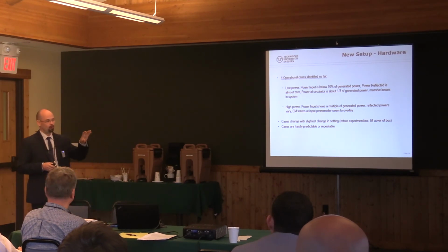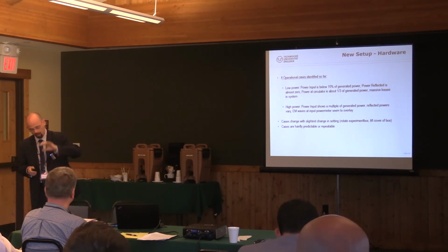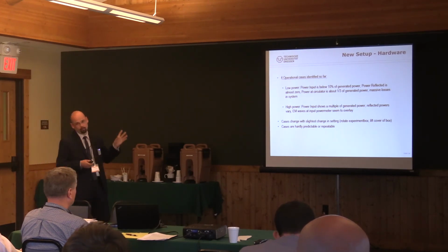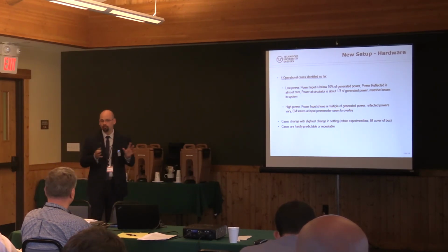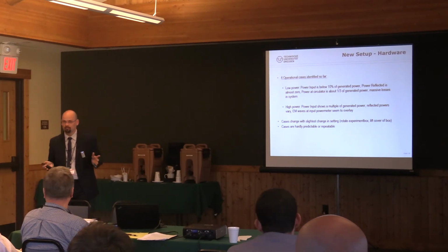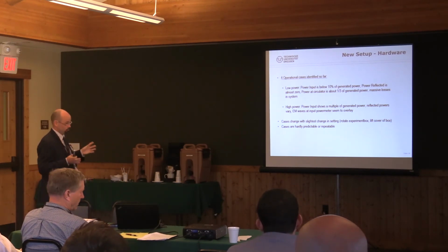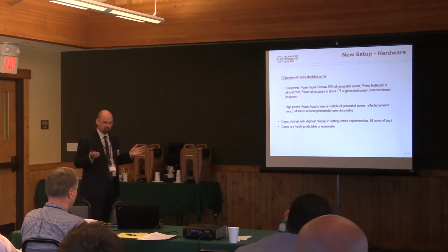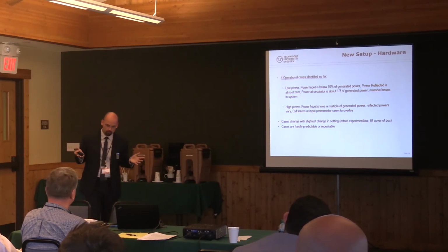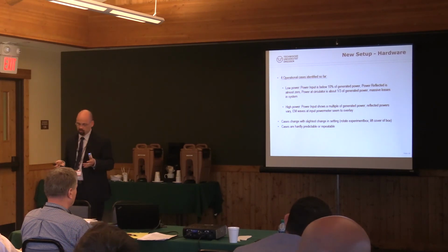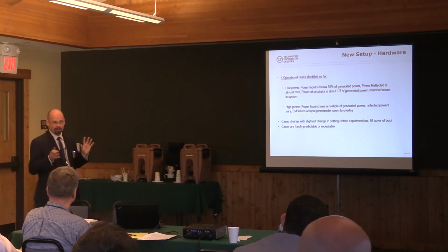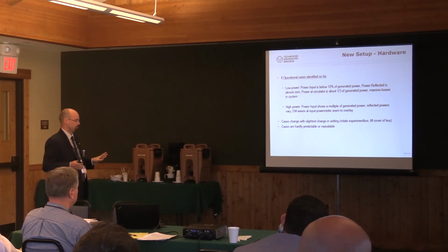Reflected power from our chamber to our amplifier was a bit more than zero, 1 or 2 watts, or perhaps a third of the generated power. But I couldn't figure out where the power goes. So perhaps I think about massive losses in the system. Perhaps we have some current loops, radio frequency loops, capacitive coupling to our mu metal shielding. At the moment I don't really know what it is.